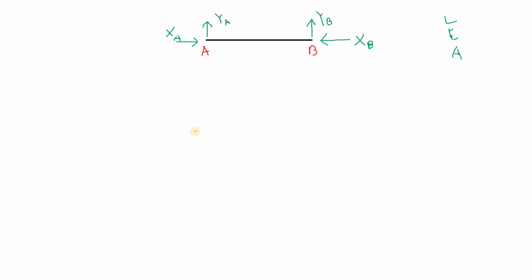Now, we already know that truss members don't have any flexural or shear stresses, because trusses don't have bending moments or shear forces on them. In that case we're going to neglect the shear stiffness and the flexural stiffness as well, because there are none.